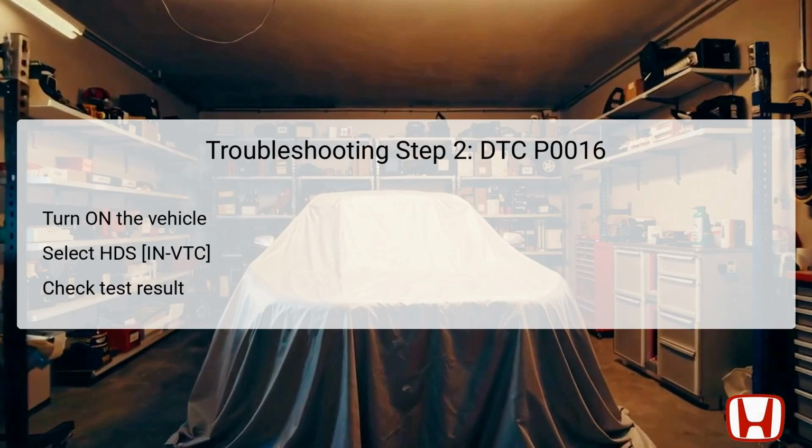In the second troubleshooting step, you will need to turn the vehicle to the on mode, which activates the necessary systems for diagnostics without starting the engine. Once in this mode, utilize the Honda Diagnostic System, HDS, and select the in-VTC function. This diagnostic tool is critical for assessing the variable timing control system's operation.